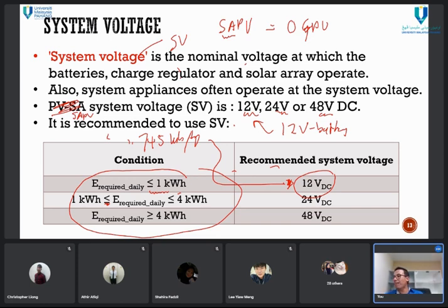And for the rest, you are going to put your batteries in parallel to get more storage capacity. But that's a different issue. When you connect in parallel, make sure you have an isolator between the batteries, to avoid sparks and safety issues. If you disconnect directly in parallel, there will be a bit of spark. Better to use an insulator, or put an isolator or fuse between the batteries, if the parallel connection is large.